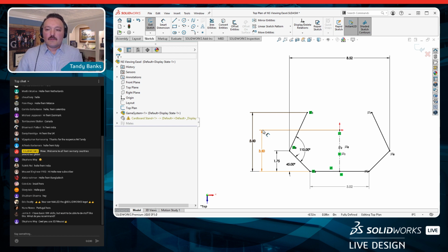Again, kind of being an old schooler, been around SolidWorks for quite a while, I'm still pretty particular about the commands and stuff that I use. I still run it the way I did in the 2000s. But the Control key, along with the numbers up at the top, is a great way to put that left hand to use. And so Control 5 is a top view.